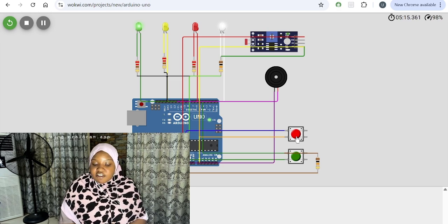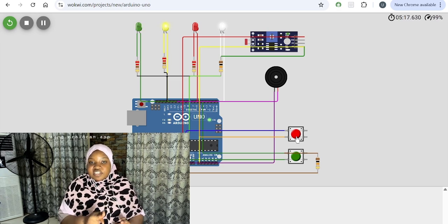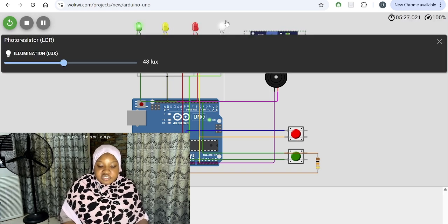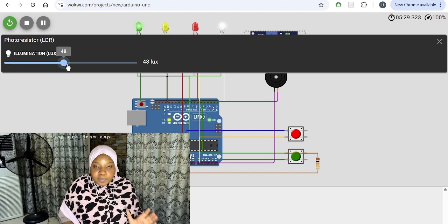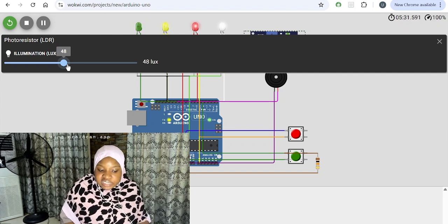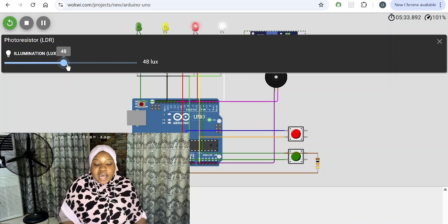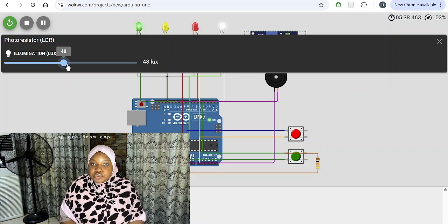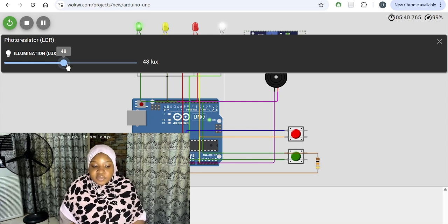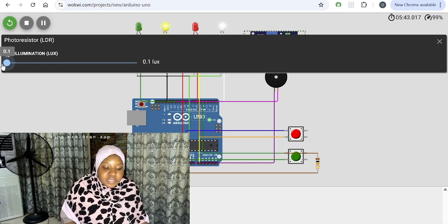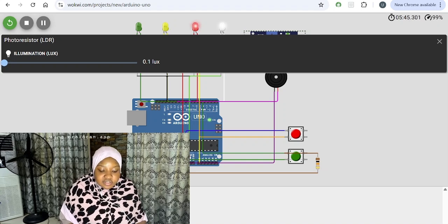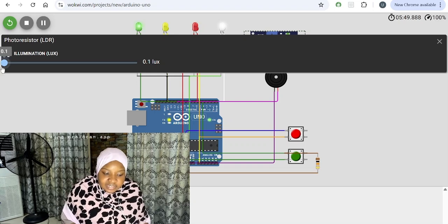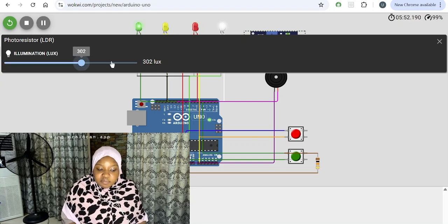So this first scenario shows three different subsystems working together. How did we get to this, the street light lighting up? At which part would it light up and at which part would it go off? So I calculated a threshold which would show daytime and then nighttime. I used the extremes: 1015 for daytime, that's when it's the darkest, and 8 for when it's the brightest.